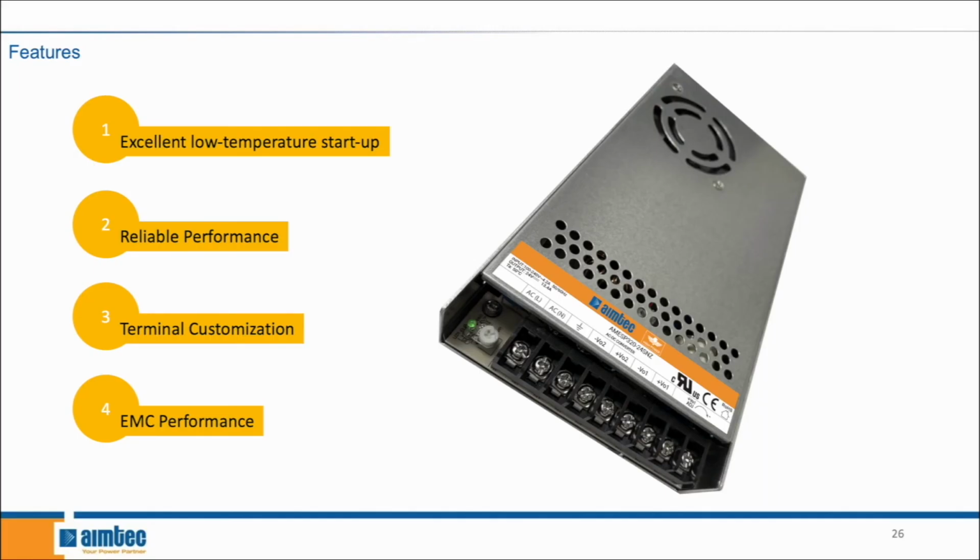Here are a few highlight features that we'd like to talk about in this course. First off, we have excellent low temperature startup. Without going through any preheating process, the new non-PFC enclosed power supplies can be started up within 4.5 seconds at minus 30 degrees Celsius, while the PFC variants need only 2 seconds. Point number 2, reliable performance. This series delivers high reliability even in high ambient temperature environments. The capacitor lifetime evaluation method ensures the capacitors will last for a minimum of 5 years while operating at 70 degrees Celsius.